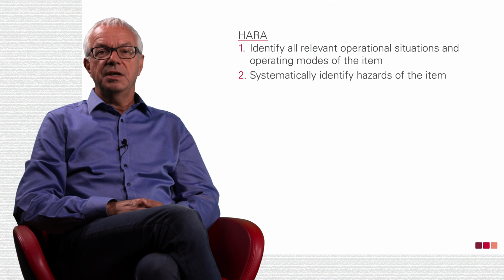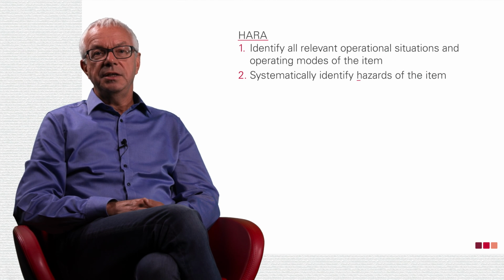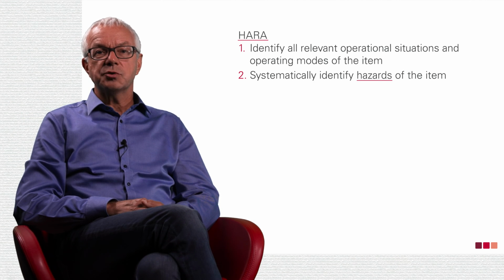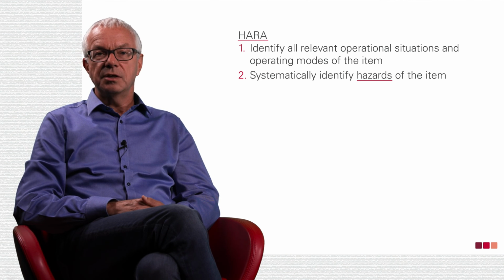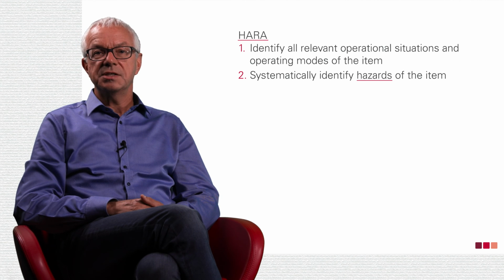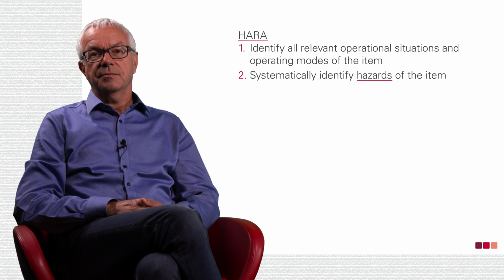The second step is to imagine risks to life and limb. You should write down any hazards that could arise either from a fault in the item or from reasonably foreseeable misuse by a driver. Hazards to passengers and other road users have to be determined on a vehicle level. One example of a danger posed by adaptive cruise control is unintended acceleration. Or the driving lights present a hazard if they go out unintentionally.